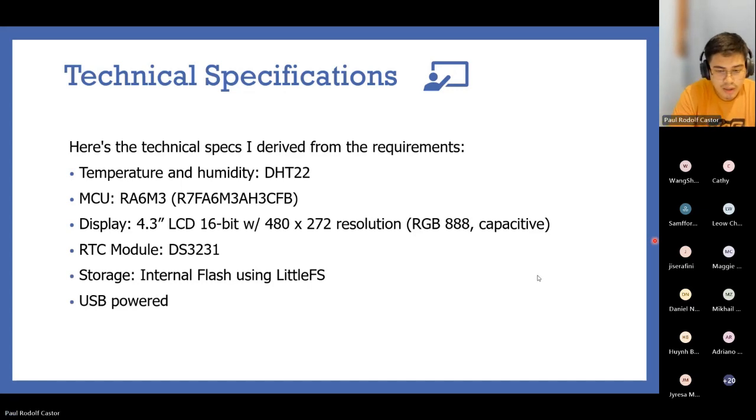So remember, this selection is directly limited by the requirements. Let's say the project needs humidity accuracy of plus or minus 1% and temperature accuracy of plus or minus 0.5 degrees Celsius, then we need to eliminate the DHT22 and look for some better alternatives. And the process of choosing the best component within specs is called component selection for electronic product design.